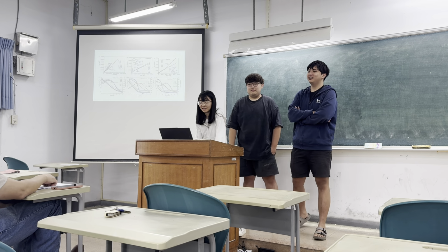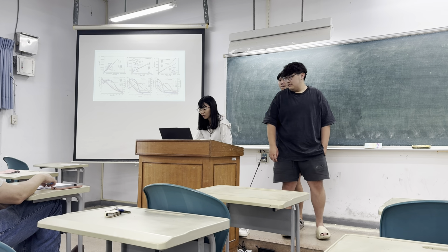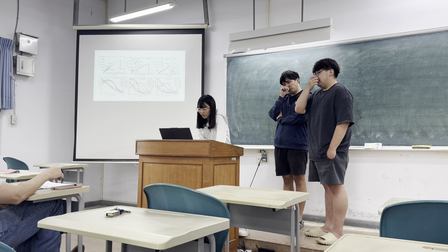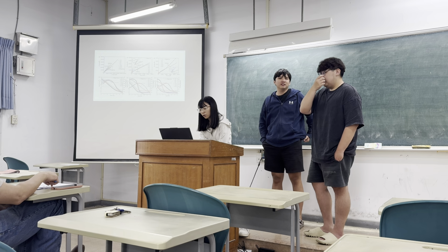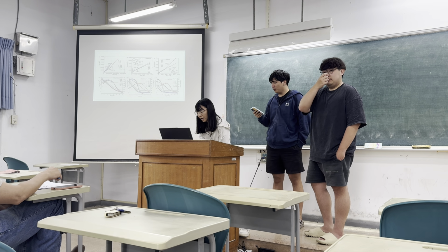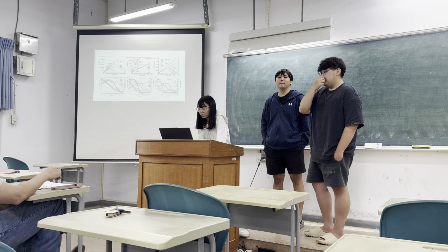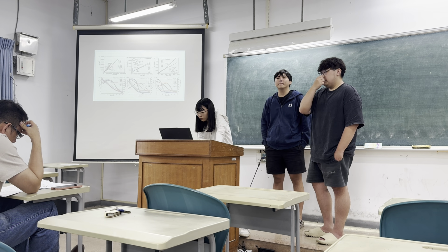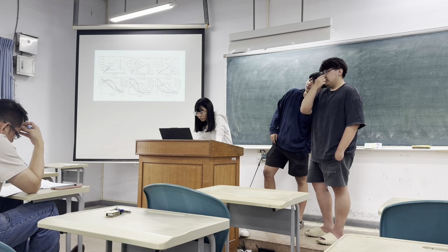The size of the semicircle is a key point. A large semicircle means a higher resistance and better corrosion protection. First, for C1 and SS, samples A and B, the semicircle becomes larger from day 1 to day 21. This means the film forms a stable protective film over time, which improves its corrosion resistance.